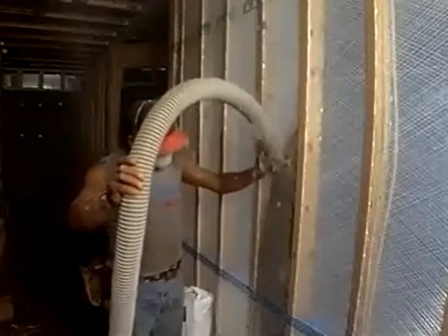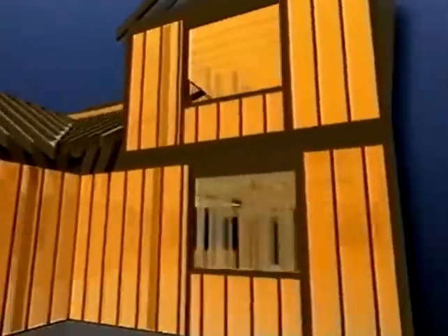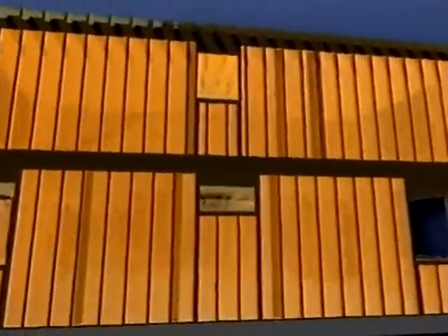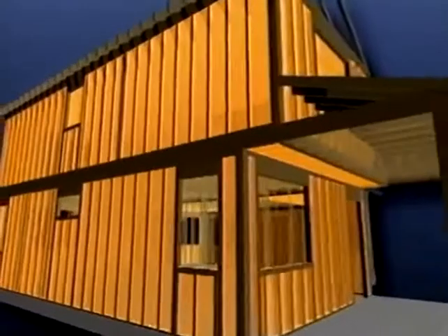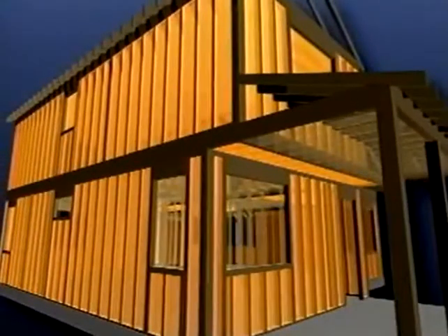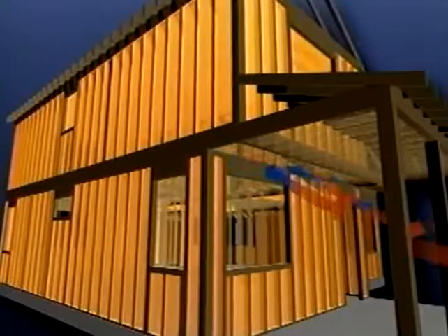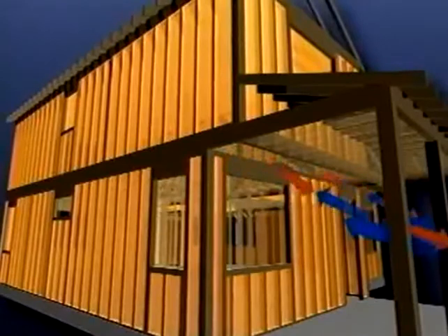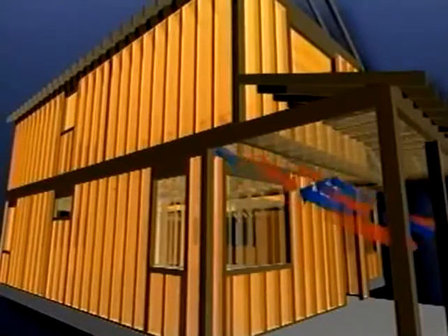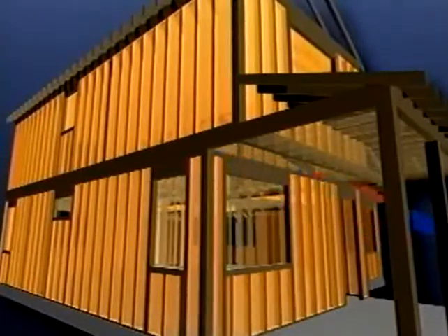In order for an insulation job to be effective, it must be free of voids, holes in the thermal boundary. Remember, the thermal boundary should wrap around the entire house like a blanket and protect it from unwanted heat loss or heat gain. Holes in the thermal boundary allow unwanted heat in during the cooling season and expensive heat out during the winter. This can cause moisture problems, energy problems, and comfort problems.